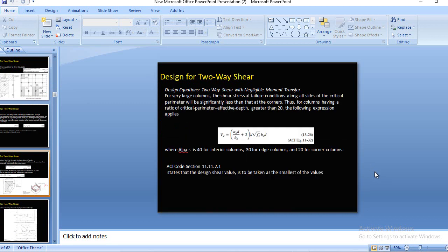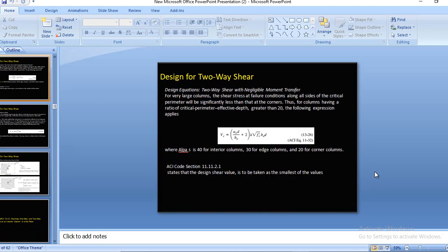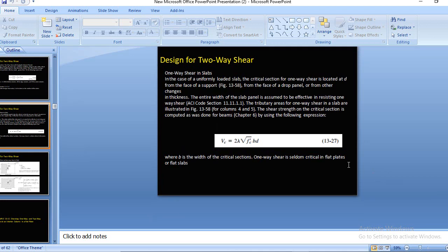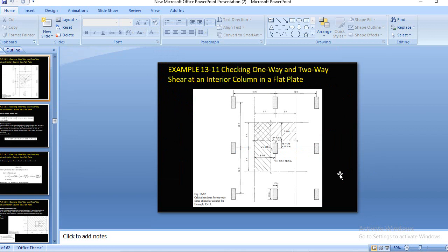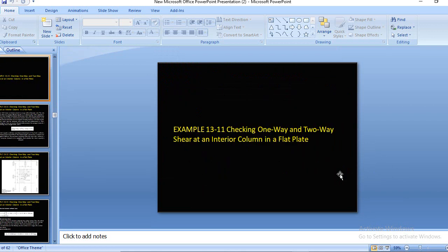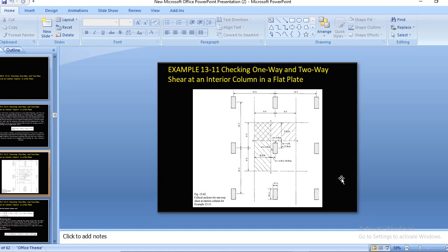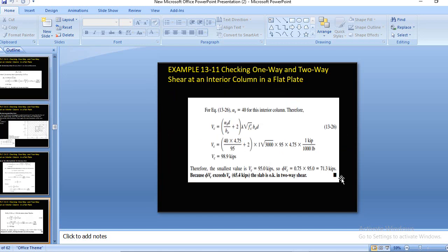Although in those lectures we tried our best to avoid shear reinforcement in a flat slab system because it makes the design uneconomical, punching shear is a governing criterion, so most of the time it is needed. So we have different arrangements: column capitals, drop panels, bent up bars, shear heads, studs, and we did so many examples on them.